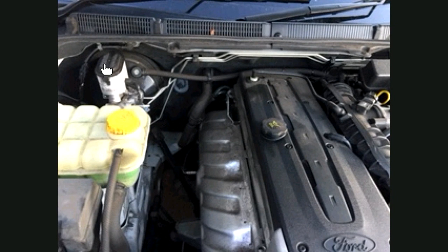Now this is your brake fluid here, and it will pull the shaft along and help you put your brakes on. Okay, and this is your hydraulic cylinder here, and that's where all the hydraulic fluid is when you top up your brakes. So that's what a brake booster is, and you need a brake booster because disc brakes need a lot of force to put on. Drum brakes don't, because they're self-energizing with the two leading shoes, as I mentioned before.